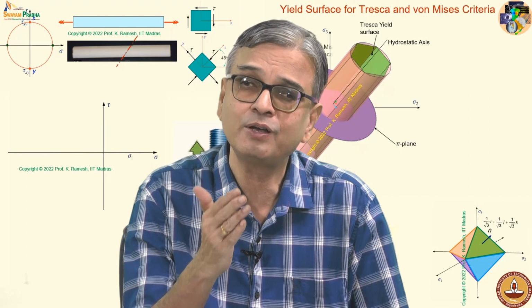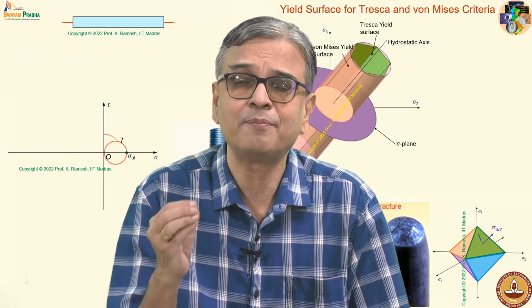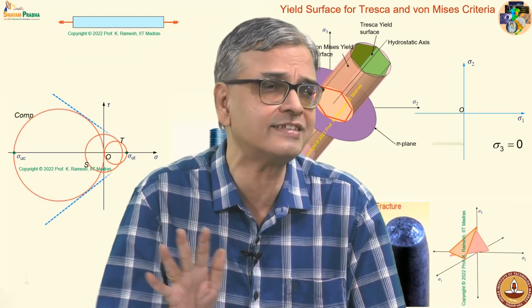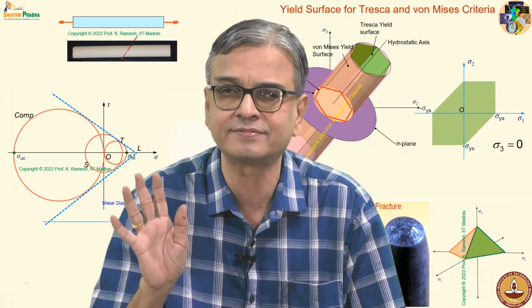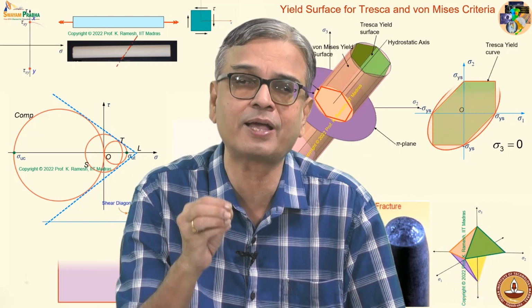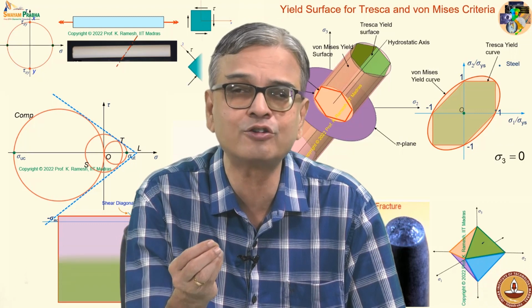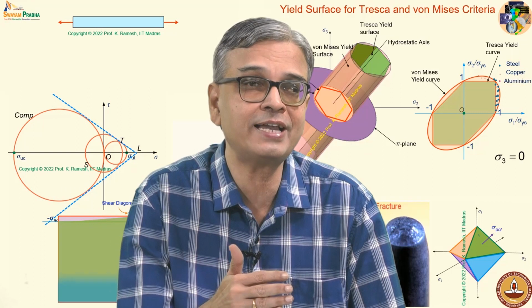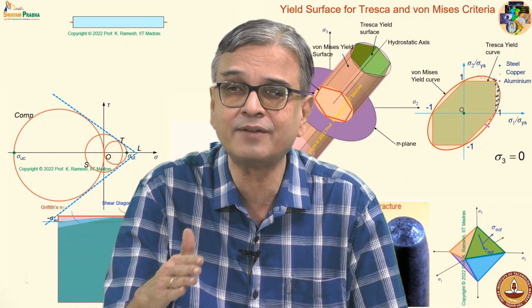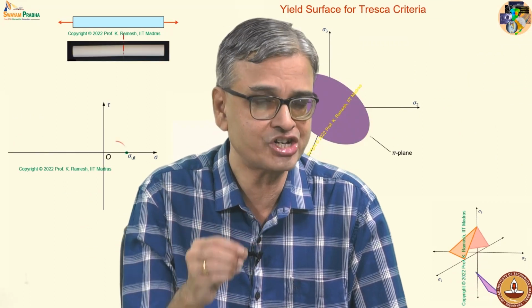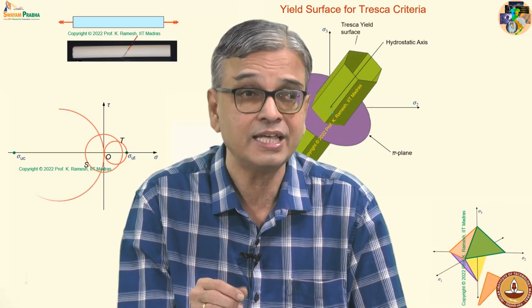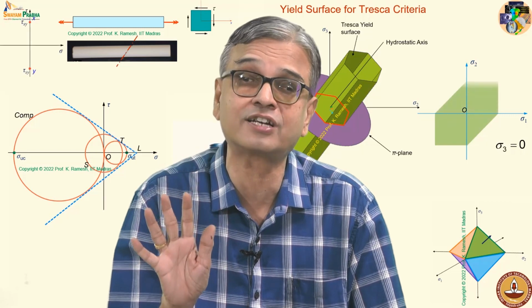We have also made an idealization that we have an elastic continuum. In reality, nothing is an elastic continuum. You have micro cracks. What people have found is if there are micro cracks and if fluid gets into those micro cracks, then failure happens much earlier. So, one of the via media people suggested is you cover this material with a thin metallic sheet, so that the liquid does not get into the crevices. Even glass has withstood very high hydrostatic stress.